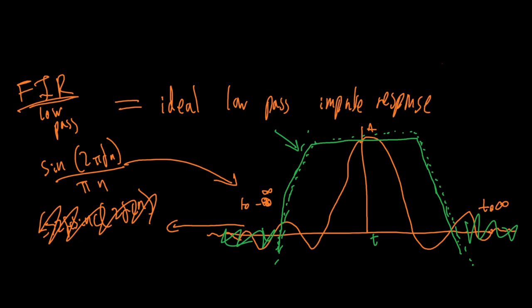Now, just another quick note on this. You can see that this sinc wave is symmetrical. Whatever happens after this line, it's the same signal. I previously did say that the reason we have a symmetrical signal is because it gives it linear phase. This symmetrical quality gives it linear phase. And just in case you're wondering, this is minus time and time. Don't worry about trying to understand that. Just understand that it's symmetrical, and symmetry allows it to have a linear phase.